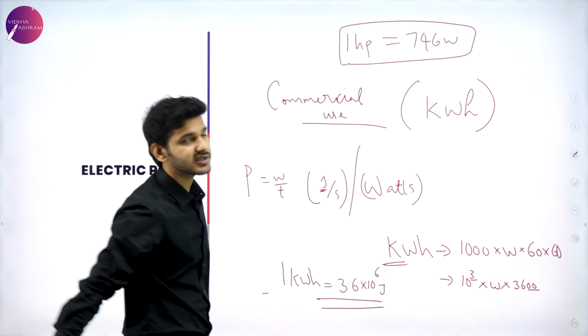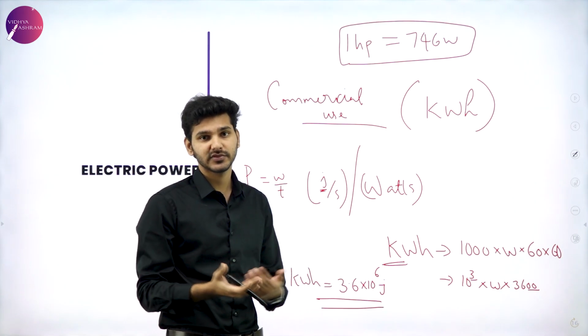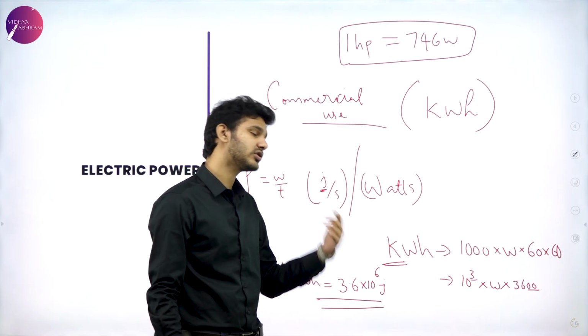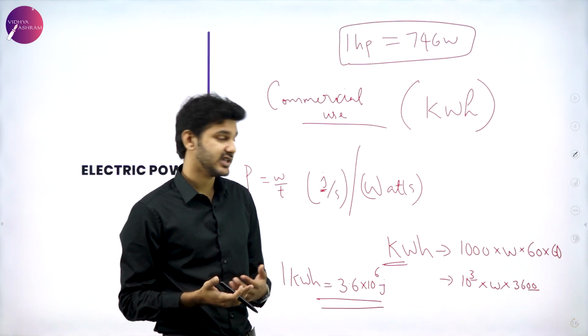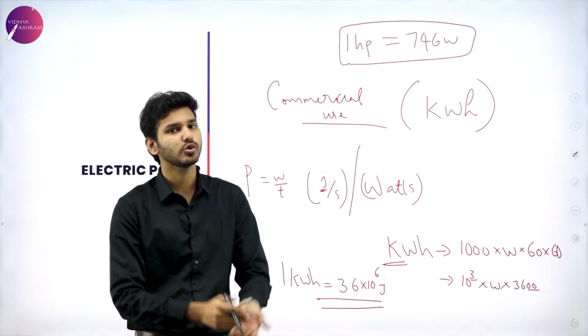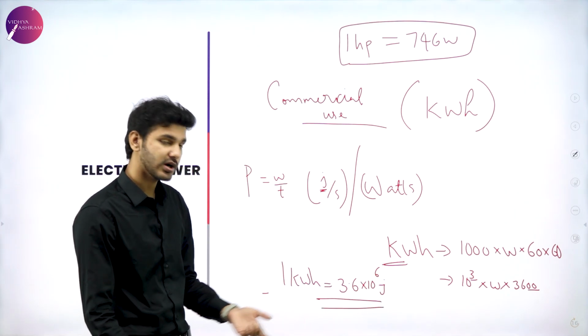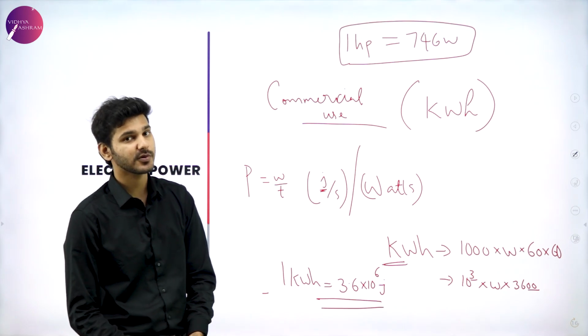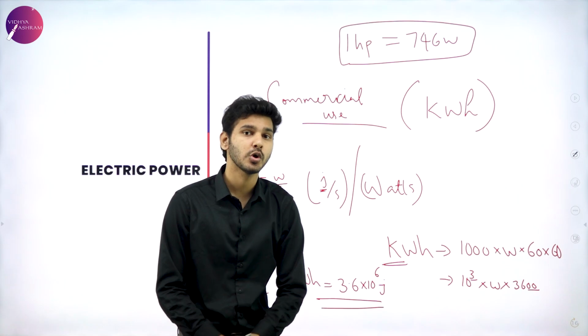So these are just two things you can remember if the question is given in a different form. That is, instead of asking for kilowatts, your question says that your household consumes, let's say, 10 into 3.6 into 10 raised to 6 joules of energy. Then don't be alarmed. 3.6 into 10 raised to 6 joules is nothing but 1 kilowatt hour. Given in terms of horsepower, you should also not be confused because horsepower can also be converted into watts.